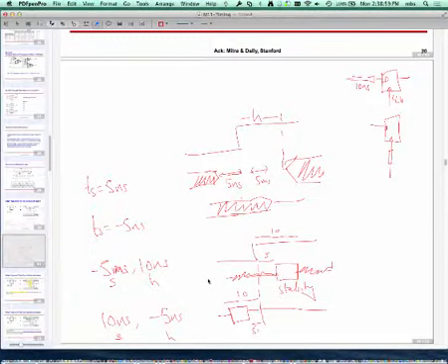Again, a very important point, which during the course of the previous homework I also said: you should never gate the clock. Clocks are very carefully designed and you should not mess with them. What you have to do is make use of the knowledge of flip-flop characteristics and combinational logic delays to make sure that the whole thing works correctly. The very, very expensive CAD design tools are catered towards just this problem, that is, verifying that the circuits would work correctly.